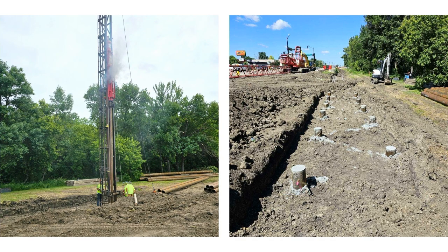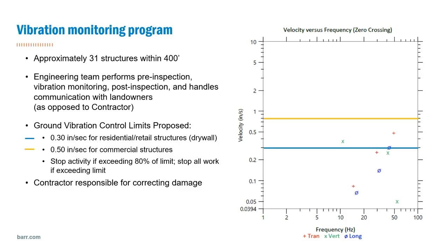And then on the right, you can see the piles in place. Like Aaron said, these are closed-end pipe piles that we then backfilled with concrete. And this has ended up getting backfilled, so you can't see any of these on site anymore. They're underground. It's just a little grassed area at this point.